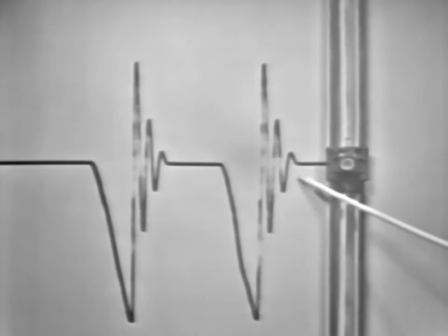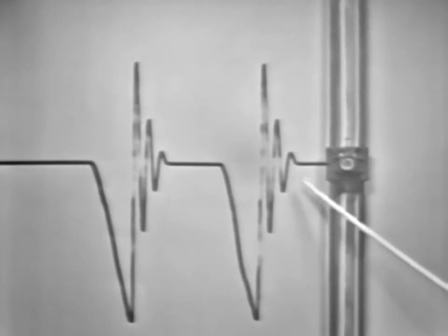What causes this damping action? What causes the decrease in amplitude? Well, in this case, the action of the oscillator is gradually diminished by the friction of the slide, the friction of the pen on the paper, the force of gravity acting on the weight, and the resistance of the rubber bands themselves. In short, the diminished amplitude on the graph is caused by inherent resistance in the oscillator. Now, only if we overcome this resistance can we make the device oscillate continuously.